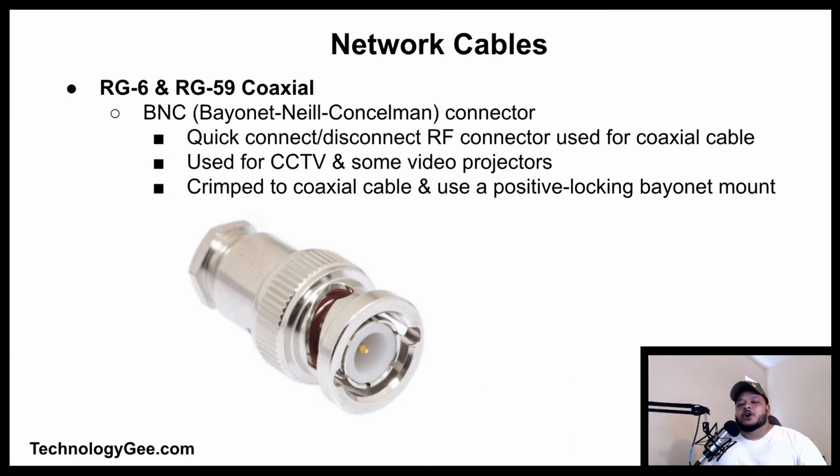So you have what is called the BNC connector, and this is a miniature quick connect/disconnect radio frequency connector used for coaxial cable. BNC connectors are typically used for CCTV cameras and some types of video projectors. BNC connectors are crimped to the coaxial cable and use a positive locking bayonet mount.